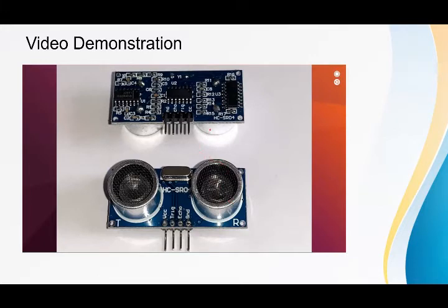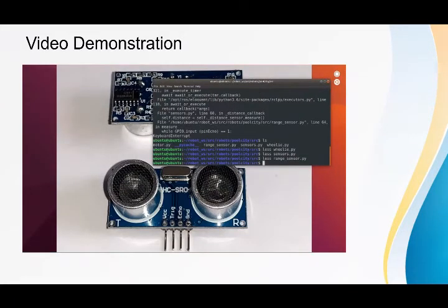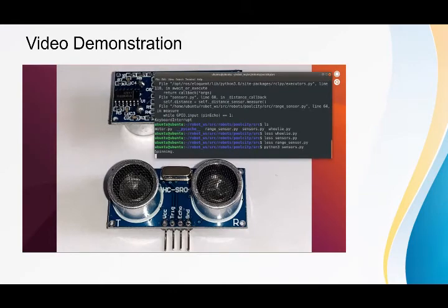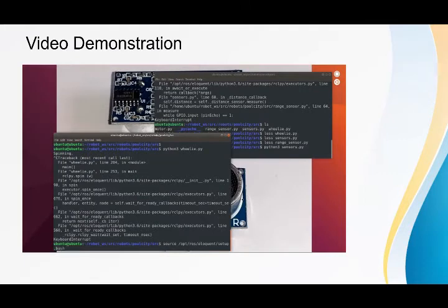All right, so we've got all our code put together and we've got it all plugged into the robot. I'm going to go ahead and start the robot up with all the nodes that we want. So the first one that I'm going to want to set up here is to start up that sensor node. So I'll let that start spinning, and then I'm going to take another prompt and I'm going to start up the robot itself.